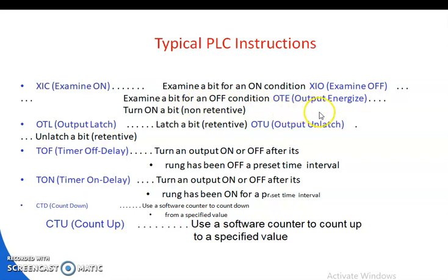OTE, output energize: turn on a bit, non-retentive. Next, OTL, output latch: latch a bit, retentive. Next one is OTU, unlatch a bit, retentive. Third one is TOF, turn off delay.